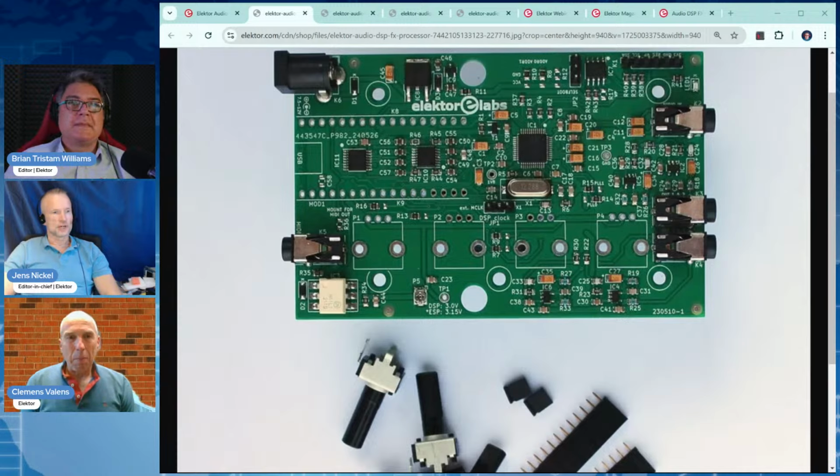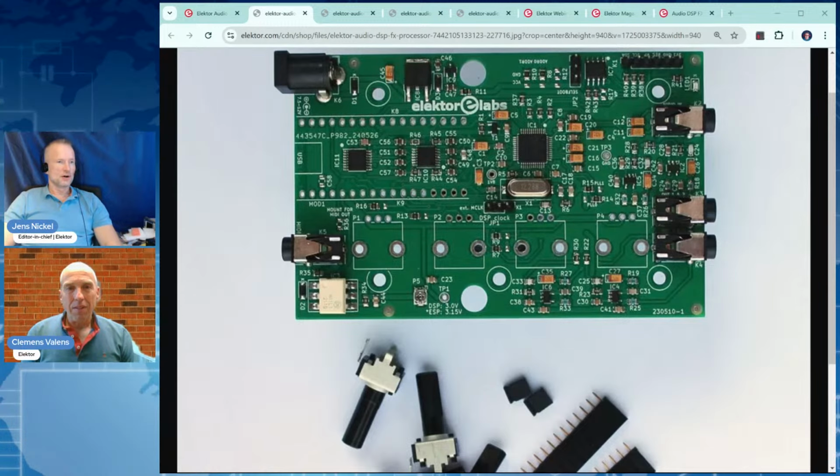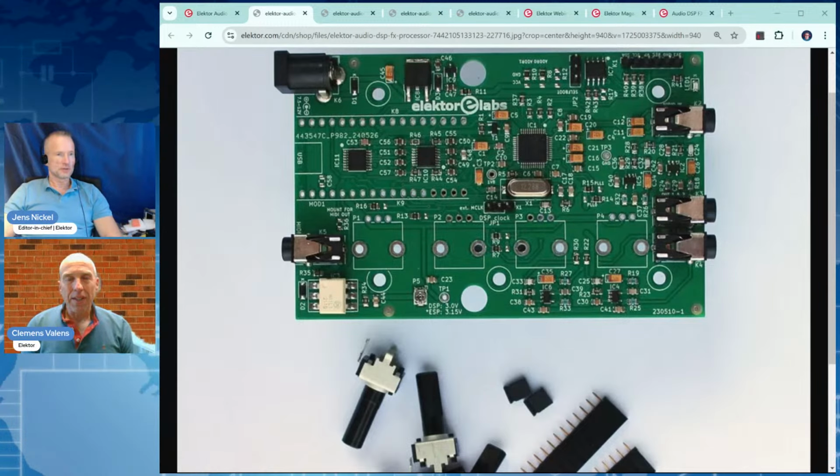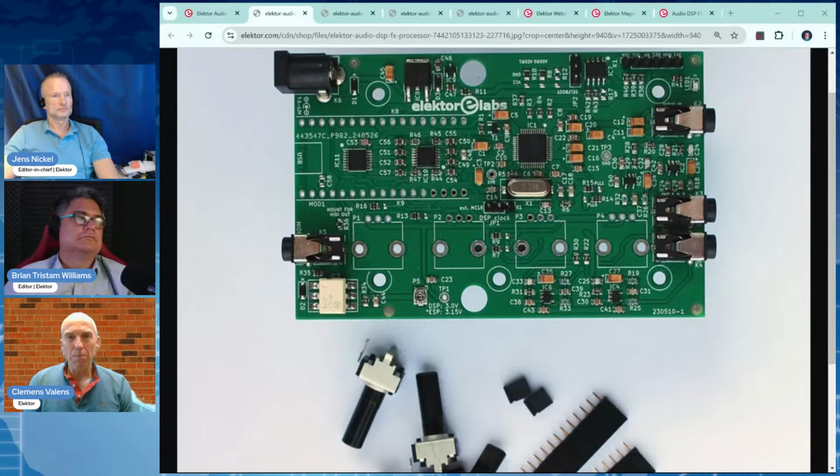Did I understand it right that you either can program the DSP on the fly directly from Sigma Studio, for example, for development purposes, or you can use the ESP as a bridge to upload the algorithms in the EEPROM, and then you can completely disconnect that device and it will always be powered on with the right algorithm? Exactly, you can use it as an EEPROM programmer for the DSP or as a wireless interface between Sigma Studio and the DSP.